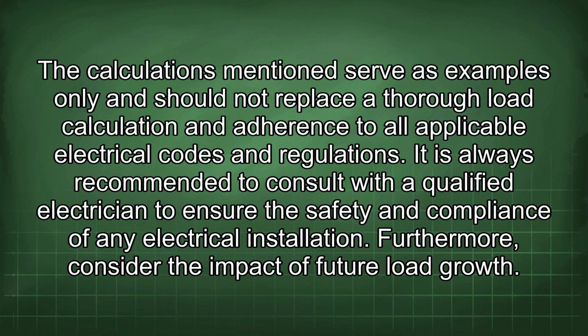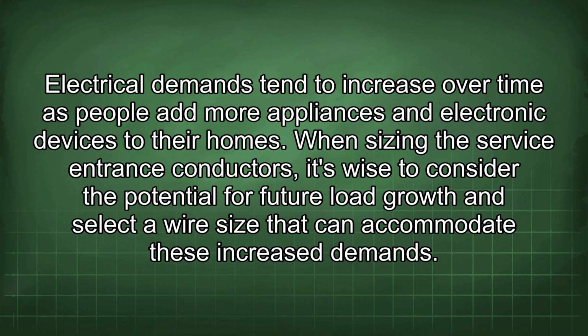Furthermore, consider the impact of future load growth. Electrical demands tend to increase over time as people add more appliances and electronic devices to their homes. When sizing the service entrance conductors, it's wise to consider the potential for future load growth and select a wire size that can accommodate this increased demand.